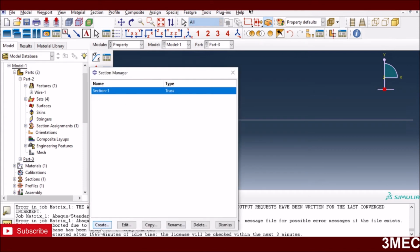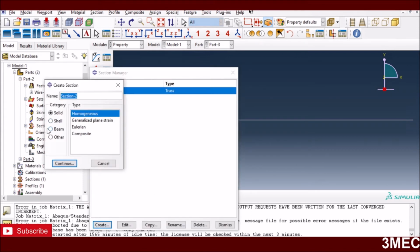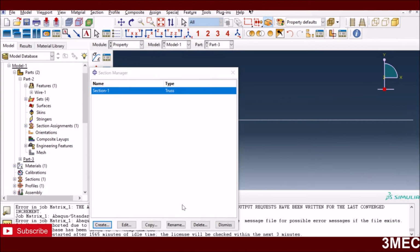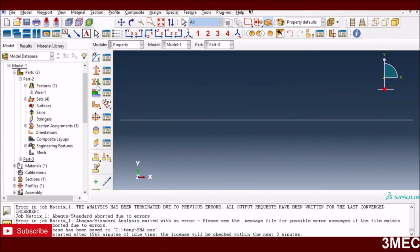Then what you do is you create a section, you create a beam section. In this case, I'm using a truss element, so I create a truss section. When I press continue, then I select this material properties and I press OK. You can also give the cross section, whatever is there. In this case, I have already defined it, so I'm not going to create another one here. Then I assign this to this part. So this is how I have done here.